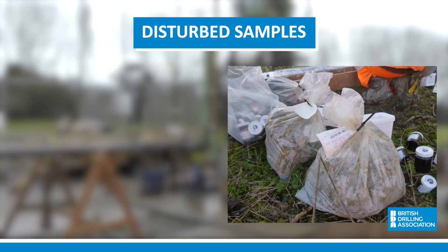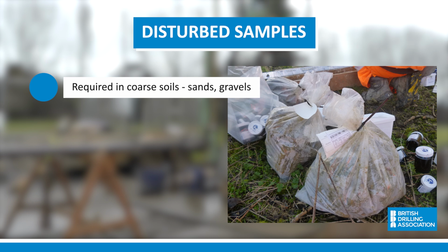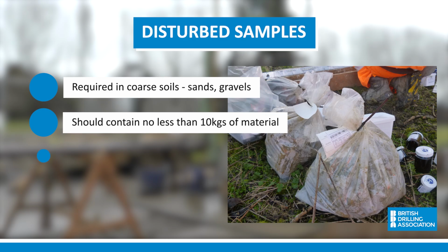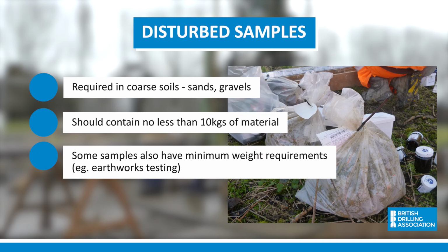Larger disturbed samples are placed in strong plastic bulk bags, and these are often required in coarse soils such as sands and gravels. These samples should contain no less than 10 kilograms of material to ensure that suitable laboratory testing can be carried out. However, when filling the bags, it is important to think about the rest of the team expected to lift and carry these around site.